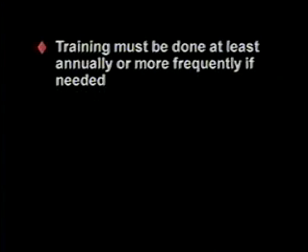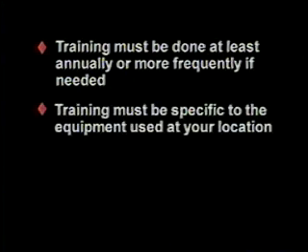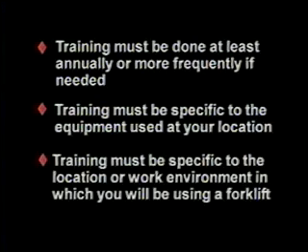Training must be done at least annually or more frequently if needed. Training must be specific to the equipment used at your location. Training must be specific to the location or work environment in which you will be using a forklift.